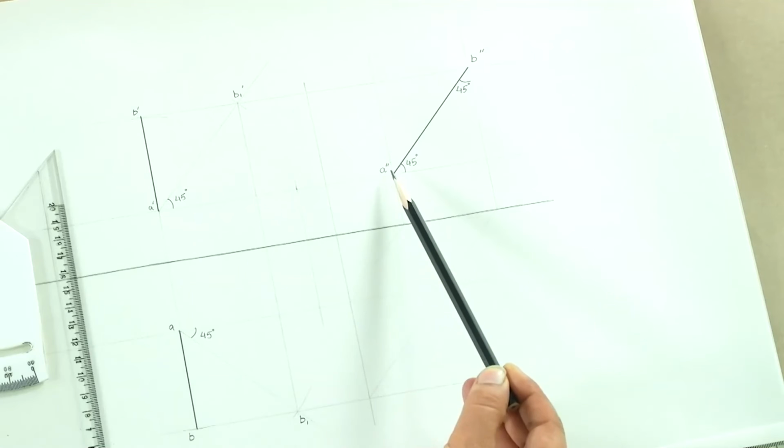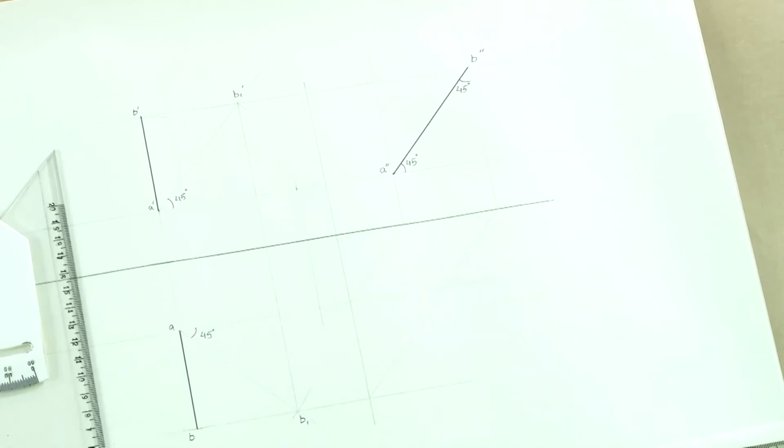Always keep this in mind that the projection lines for a point should match throughout the drawing. There should not be any ambiguity. If it is A, the projections of A will all match in either of the planes, not just in HP and VP, but also in the side planes, and then you can appropriately label it. It's as simple as that. So, I hope you've understood the projection of doubly inclined lines up till here.